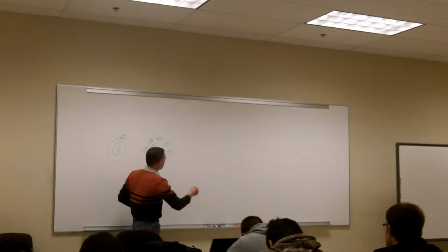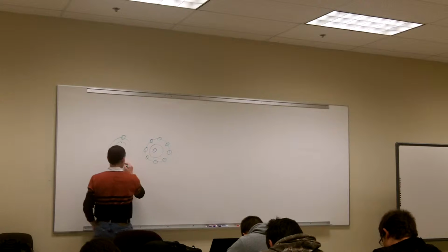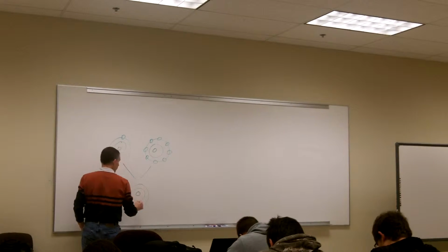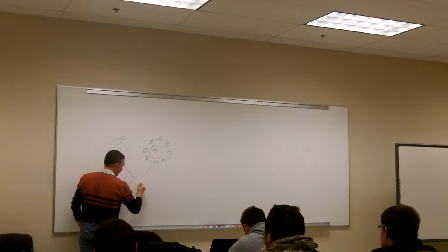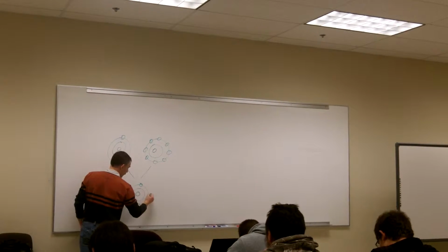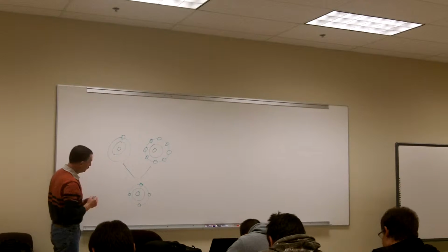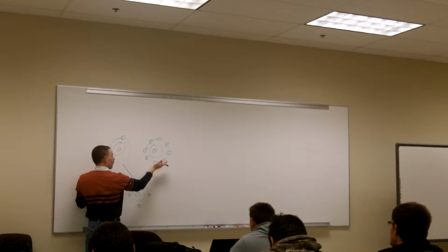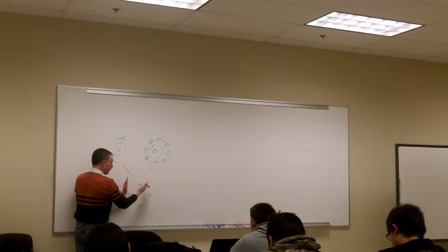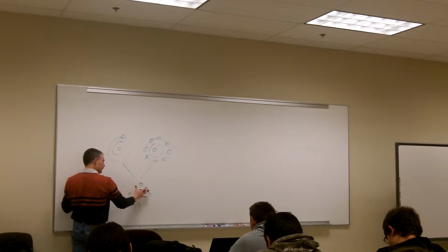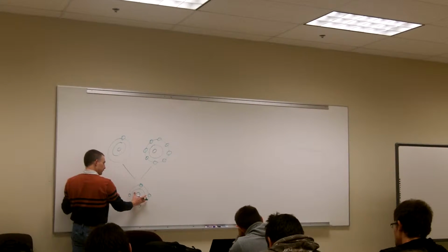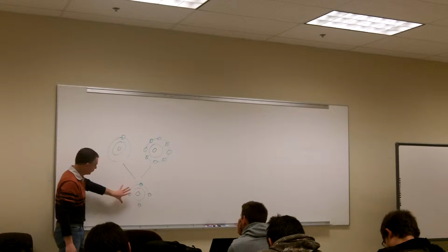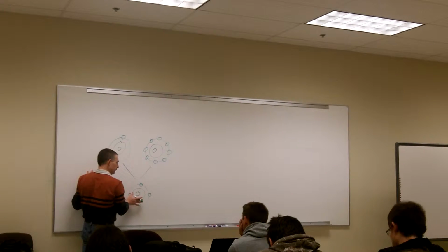So now the semiconductor is one that's in between these two. It's going to have 4 electrons on its valence ring. So it doesn't really make it either a good conductor or a good insulator. It's somewhere in between the two. It wants to hold onto its 4 electrons, but if we give it a little push, either by heat or by voltage or something like that, we can get these electrons to break free and then move to the next atom.